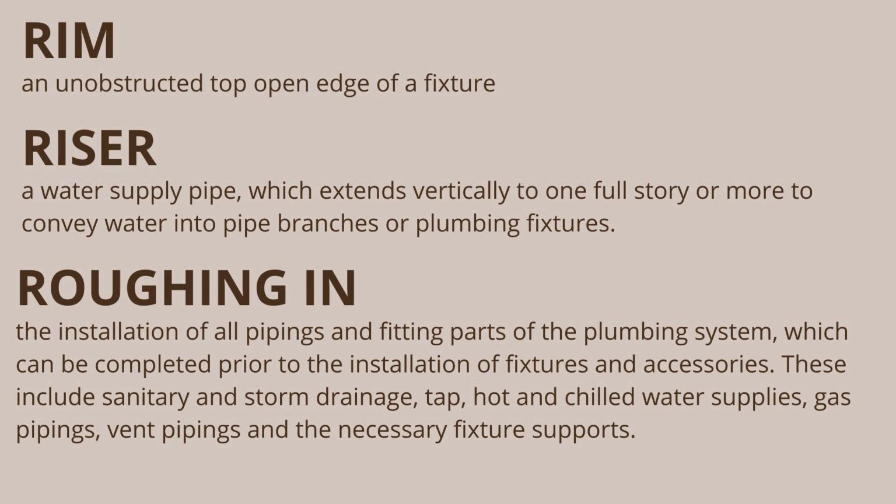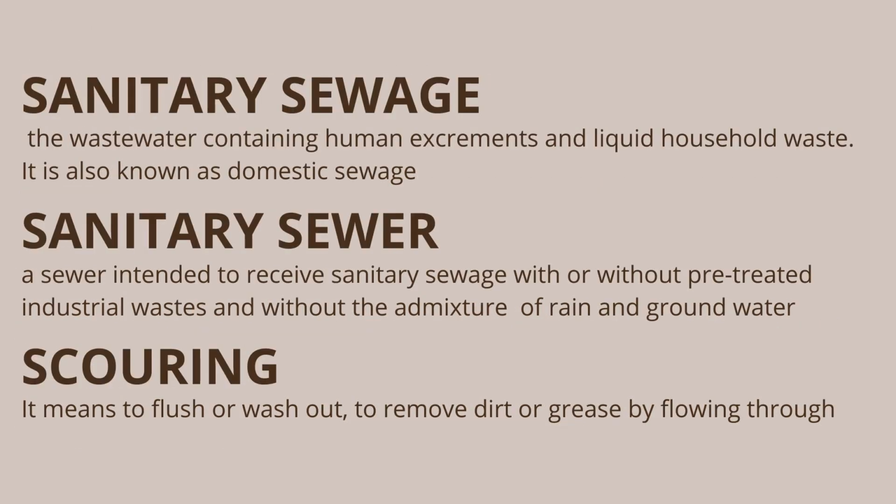Roughing in. The installation of all pipings and fitting parts of the plumbing system, which can be completed prior to the installation of fixtures and accessories. These include sanitary and storm drainage, tap, hot and chilled water supplies, gas pipings, vent pipings, and the necessary fixture supports.